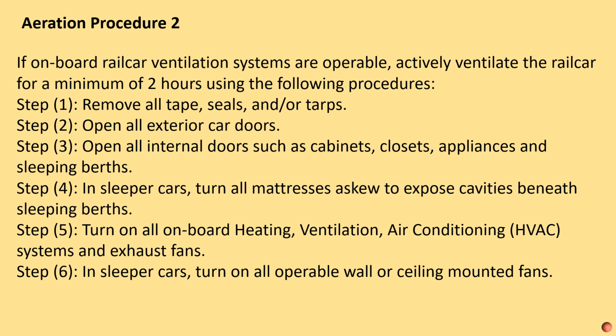Step 5, turn on all onboard heating, ventilation, air conditioning, HVAC systems, and exhaust fans. Step 6, in sleeper cars, turn on all operable wall or ceiling mounted fans.